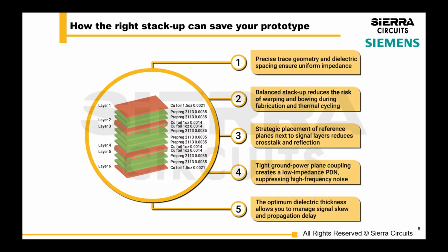There's a lot of boards that we're building right now that just require fixtures to hold the board in place as coplanar as possible during the assembly process. Even if it's a thick board, it might be too heavy, or if it's a thin board, an array is not enough to hold these boards in place during the assembly process. So understand your stack up and understand that there's no induced warpage in the stack up.